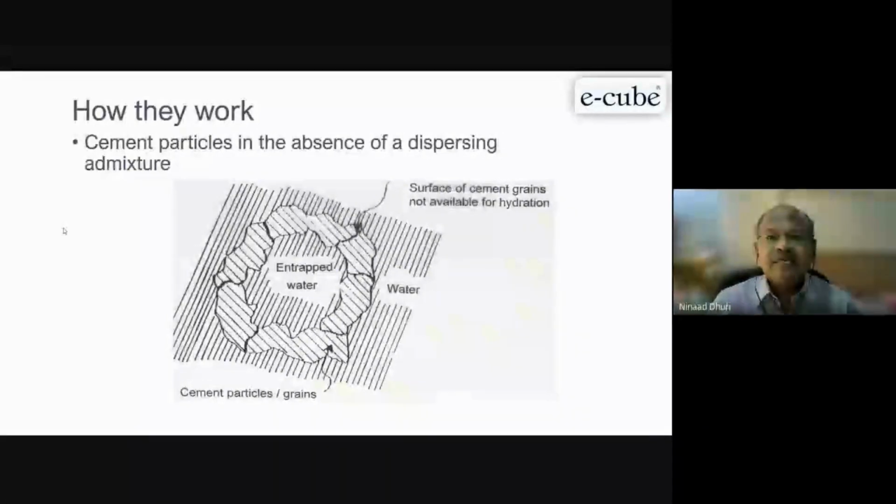When you are adding any admixture, it has to be added once you have mixed the concrete with partly water, maybe 80-90% water, and then you can add admixture to get more effect and minimum consumption of admixture. Some people or some site, maybe some batching plant, they don't have the proper arrangement for dispensing the admixture dosing systems, so they add directly into the water itself because mixing is better.